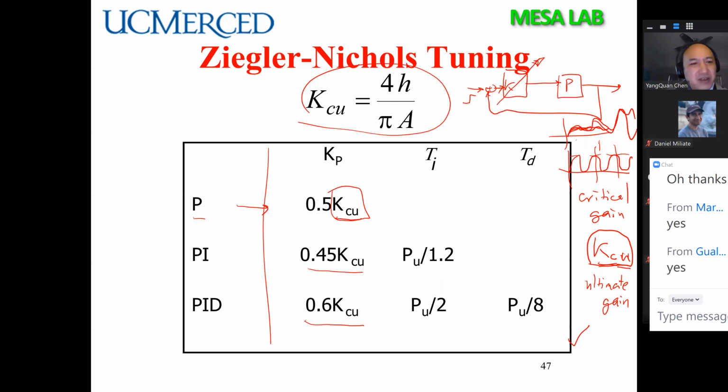The period is called PU, the ultimate period. So you measure it, put this PU here. You have KCU and PU, use this table, and you can get the second form of the Ziegler-Nichols tuning rule.